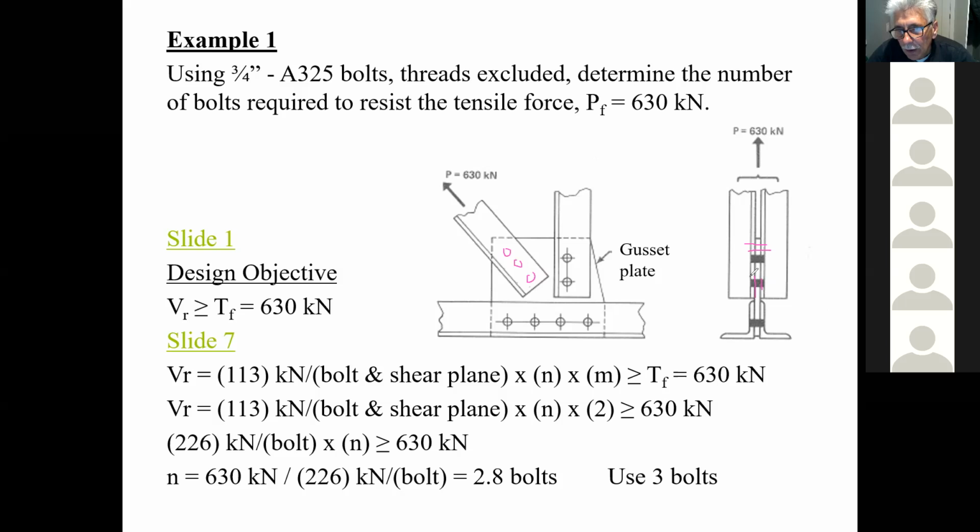The bolt would be here, like this. And let me just change color again. So when this thing is pulling this way, this force is being transferred right across that shear plane of the bolt there and right across the shear plane of that bolt there. Therefore, I have 2 shear planes per bolt. Is that a little clearer, Andrew?